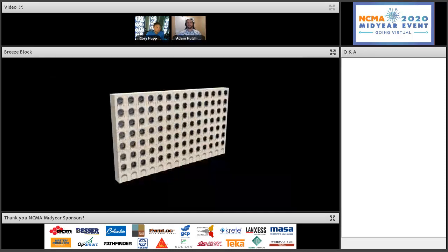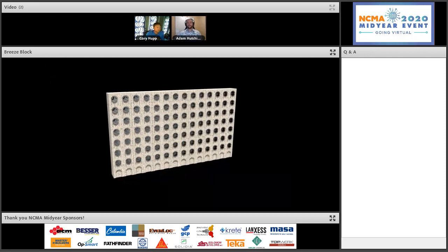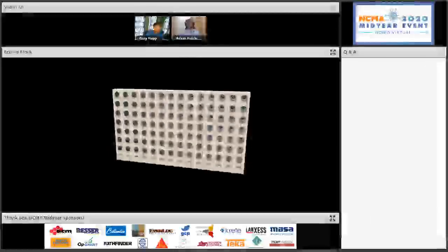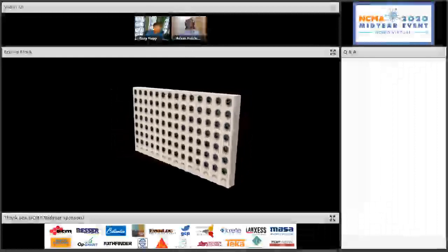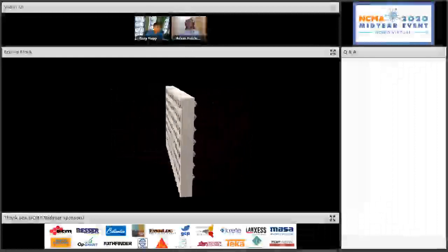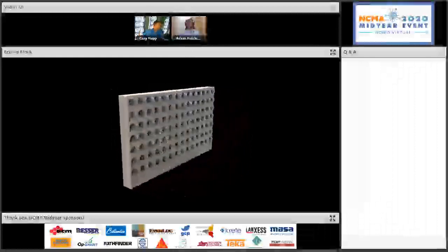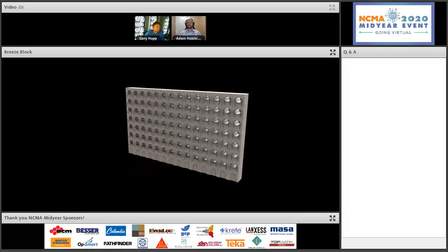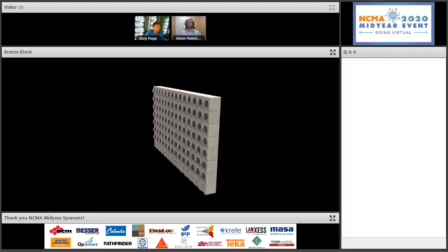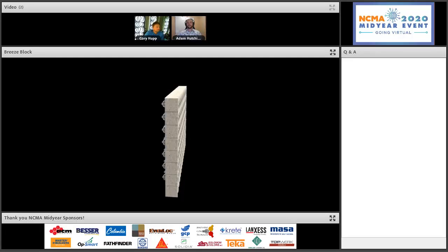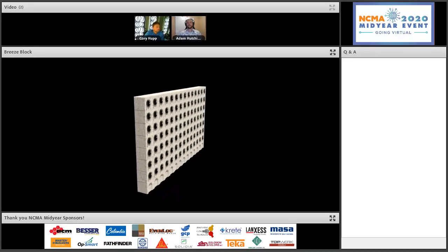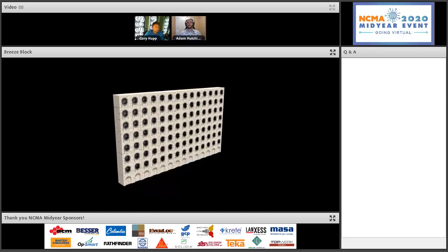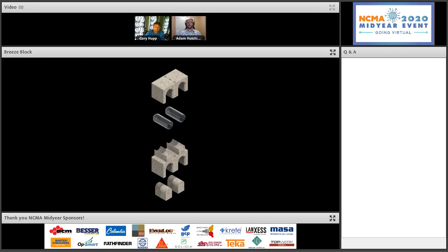The overall assembly of the wall is comprised of 3 sequential parts: our typical Breeze block module with openings for the repurposed water bottles, a top cap, and a bottom piece that fills the slot where the water bottles would ordinarily be placed. Because these blocks act as a method of passive cooling, we envisioned a number of applications where they could be used specifically in hot environments like Haiti. Not only could Breeze blocks be utilized as exterior walls of buildings, but also as separation walls around the waiting areas near medical and community centers.